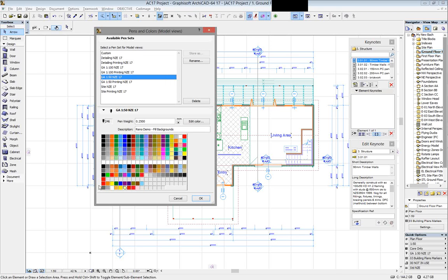But directly with regards to renovations, the renovation tool has given you more choices in how you visualize the different phases. So do you want to show fills or not? And one of the things that hasn't been done is that sections and elevation markers still don't have the ability to be assigned to a phase. So if you do have different elevation markers for existing and new, you'll still have to use layer manipulation for that.